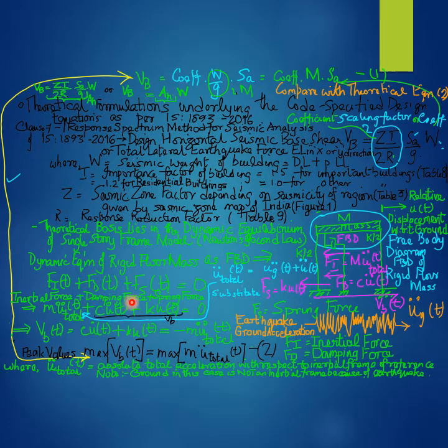The other dynamic forces under which the free body diagram of the floor mass is in equilibrium, in addition to the inertial force F subscript I, are the damping force denoted as F subscript D, where the subscript D signifies damping, that is the viscous or the natural damping of the single story frame, specifically the viscous or natural damping of the columns of the single story frame, and is symbolically represented by this dash pot.